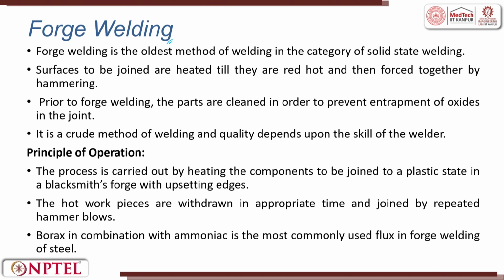Forge welding process is one of the oldest welding methods in solid state welding. The surfaces to be joined are heated till red hot and then forced together by hammering. So, you keep a base plate, you heat it, then you forge it. You can keep a die and do it, or you can keep a hammer and do it. So, this is how it is done.